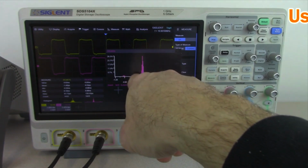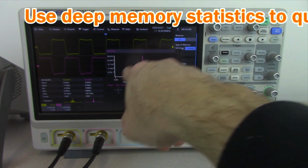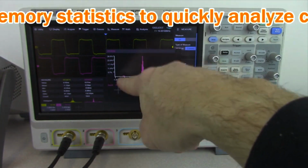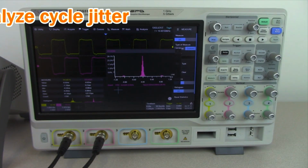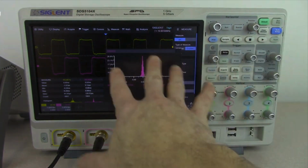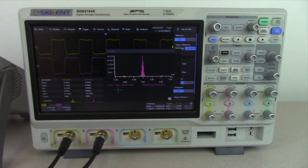That's very easy to see as we start to collect those statistics. Every once in a while, we get a bin over here with the jitter, and then we get the rise time here. So the cycle time jitter is actually fluctuating between these two. It's a very, very easy way to take a quick look. We'll let the clock run for a period of time, and then we can see whether the clock has some kind of deterministic or quantized jitter.